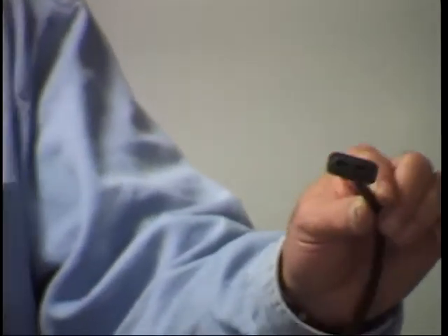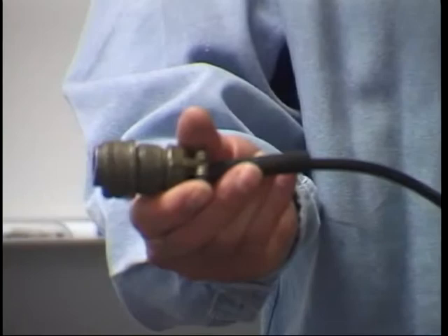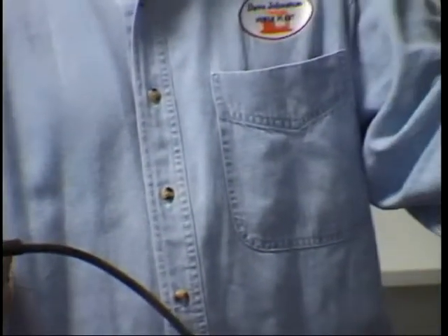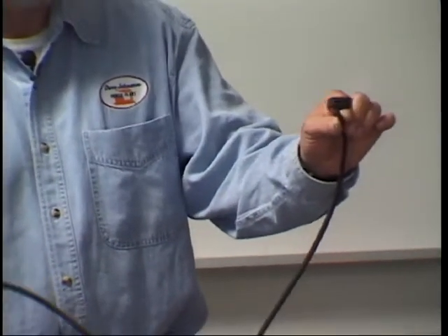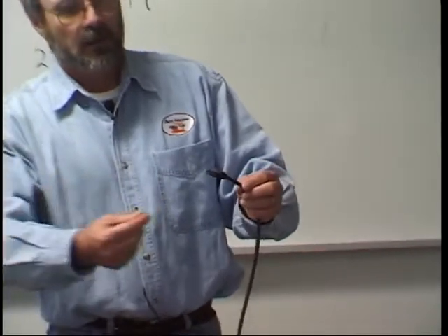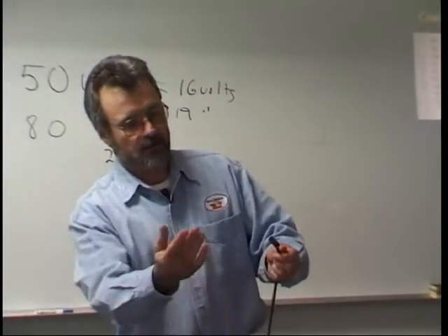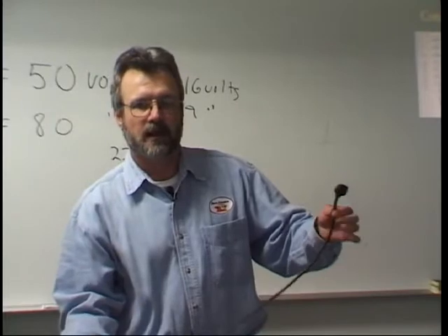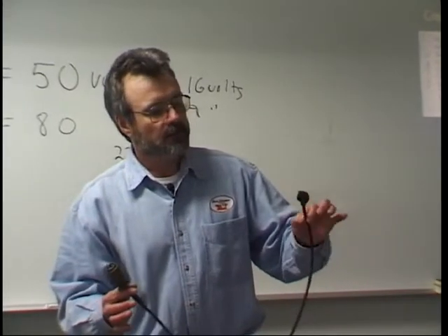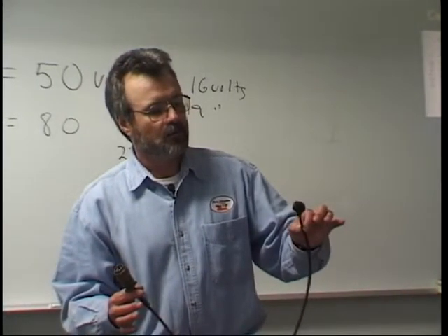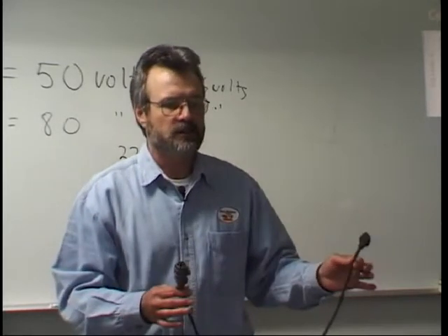and the other end would then plug into the wire feeder like so. But again, it's just two wires, and all you're doing is closing the circuit with it. I could take a piece of TIG wire and bend it and stick it down in there, and again, I could close the circuit and make that run. So these were not nearly as good as the new ones.